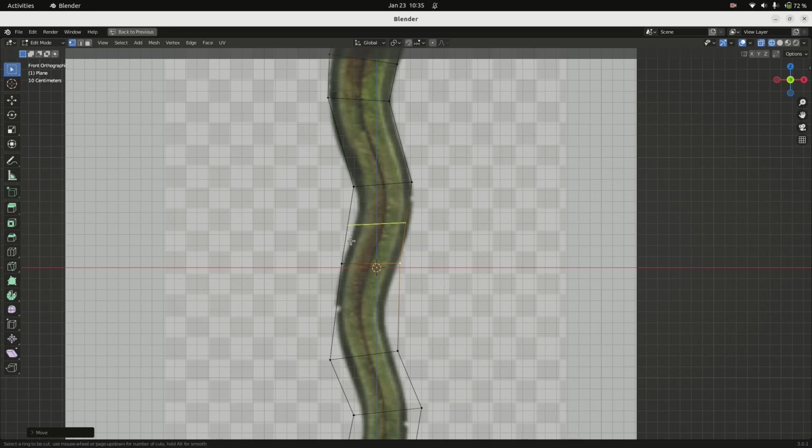will allow me to cut a face, but keep the topology. So what that means is that the plane, or the rectangle that's defined by, or the quad that's defined by these four vertices, is not going to change. It's going to be kept in the same shape. All I'm going to do is then bisect. I'm going to cut this line in half and this line in half and add another line and connect them.